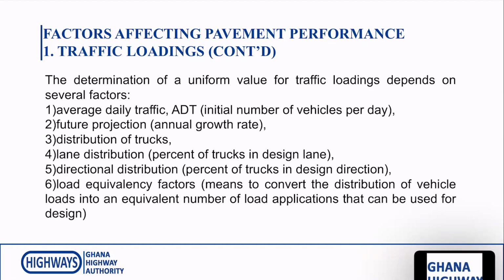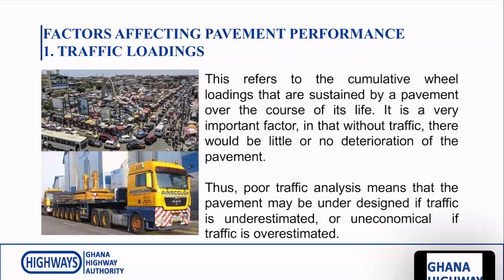Now, if you look at this slide, you see that on top of it, we have a lot of vehicles. There's a serious traffic jam. And underneath that, we see another, it's an automated truck, but there's no traffic jam. Now, for pavement design considerations, the traffic volume is not too important. The important thing is the traffic loading that causes the damage on the pavement.